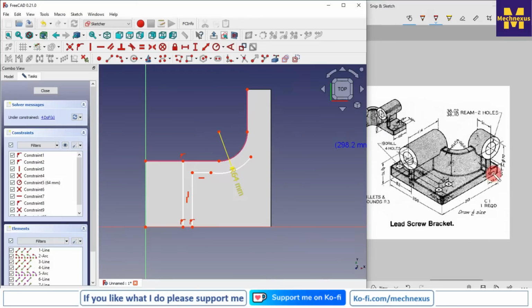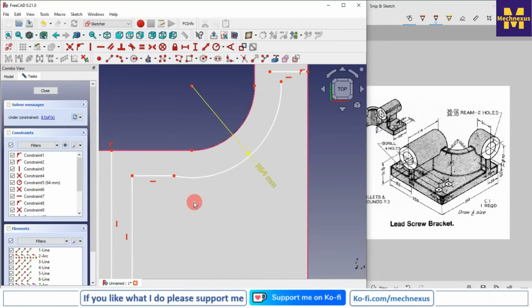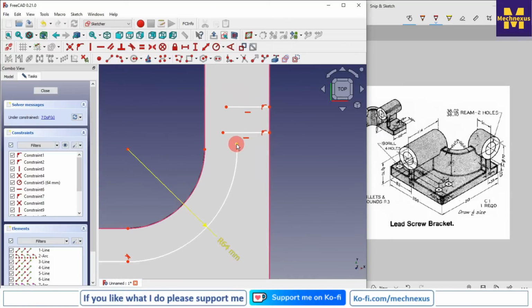And from here we have also create this type of a rib. So for this I will project the geometry, select the line tool, again. Now this is the 64. Now we will move it and I will add the tangency relation here, and I will merge these 2 points, say merge.